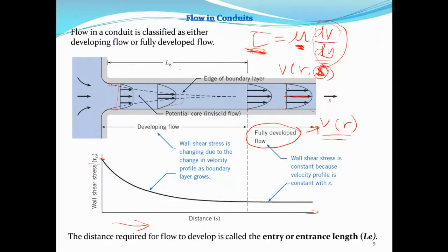But before it becomes fully developed, the fluid particles are accelerating, because the velocities of the fluid particles are changing. If you look at the center line, you can see this is shorter, this is bigger, so it's increasing, that is, accelerating. When the velocity is increasing with time, we say the fluid particles are accelerating. So that is the region within which the fluid particles are accelerating.